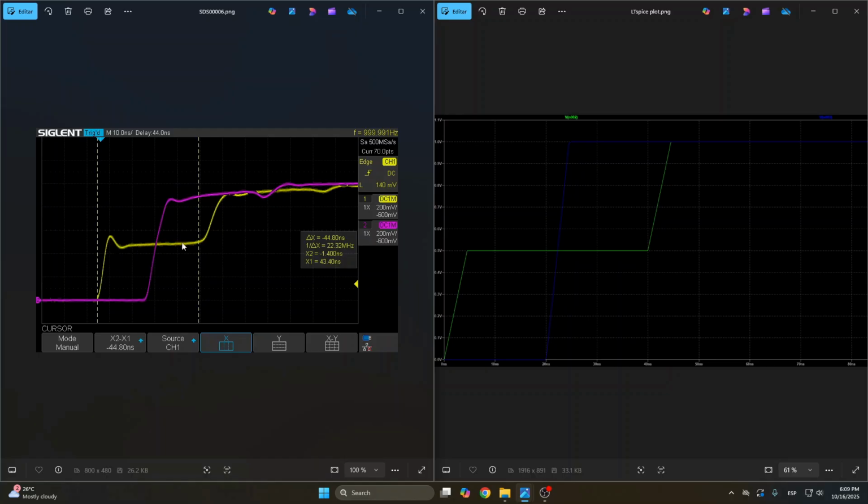In the real world, my trace is approximately 18.5 nanoseconds, but I also have some short segments of coax cable that add additional delay, and it's hard to measure that delay exactly, but clearly we are getting some extra delay. Instead of 40 nanoseconds, we are having 44 nanoseconds, so those cables are probably adding a couple of nanoseconds of delay each.